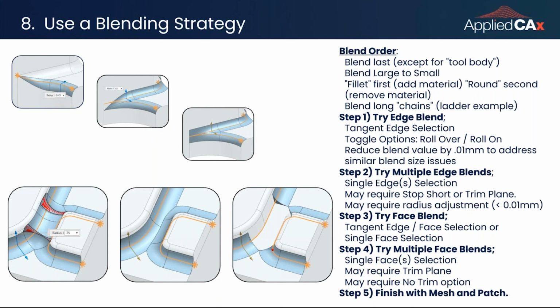If you can't quite get what you want with the edge blend tool, you can start using some of the other blending tools. The next best one would be the face blend tool. And then, as always, if you can't get any blends to work, then you're going to end up creating some surfaces and patching that stuff in there.